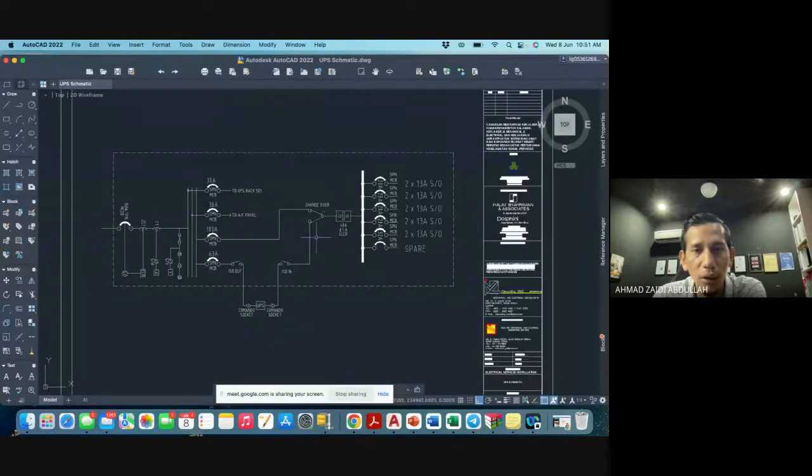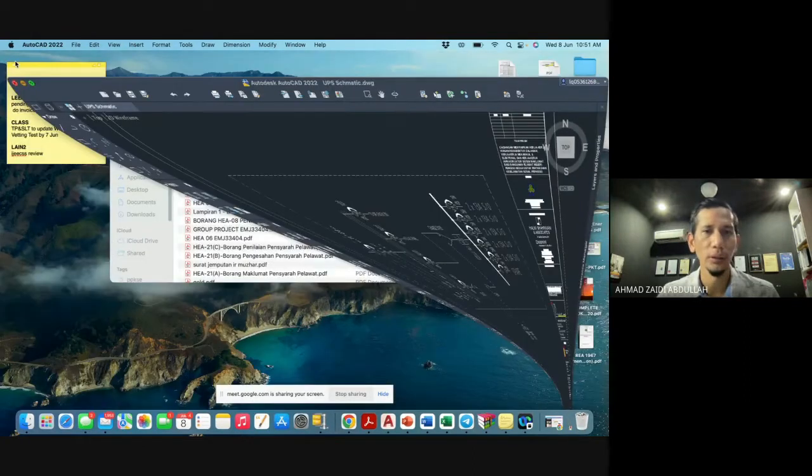If you design a UPS without a changeover, then when you switch on the supply, it will blow up here. Because you have two supplies at the same time, the UPS and the grid. It is dangerous, right? So please make sure. Okay, settle.